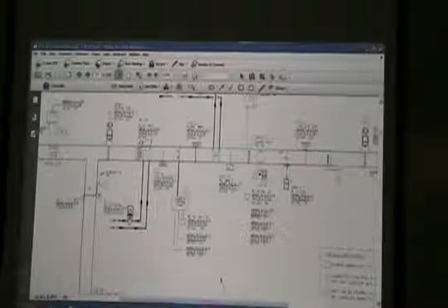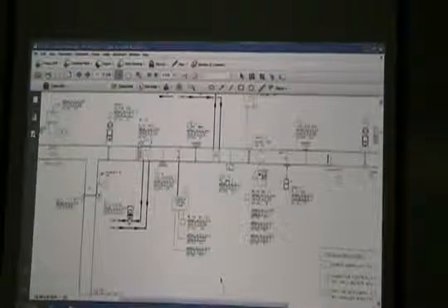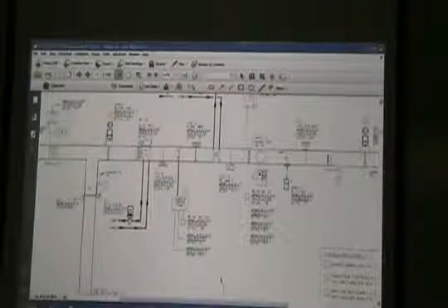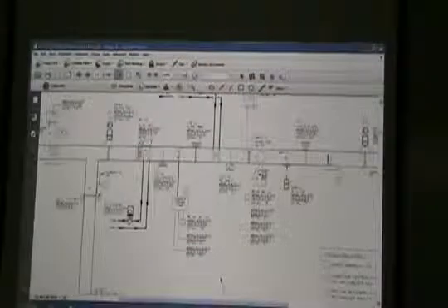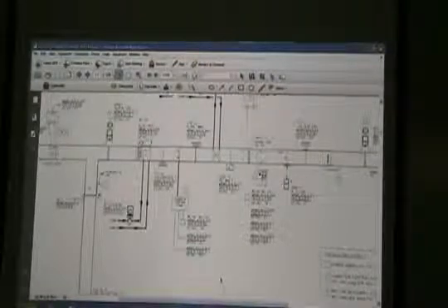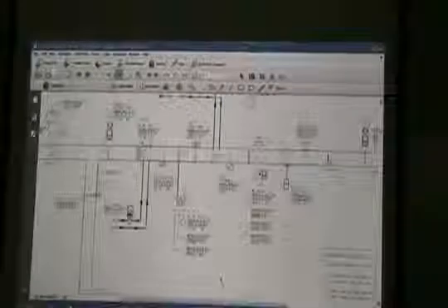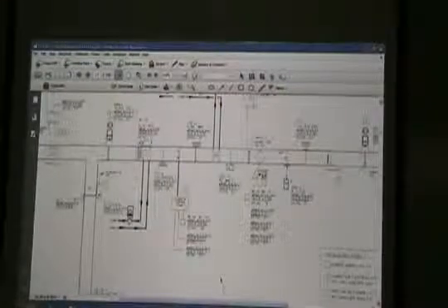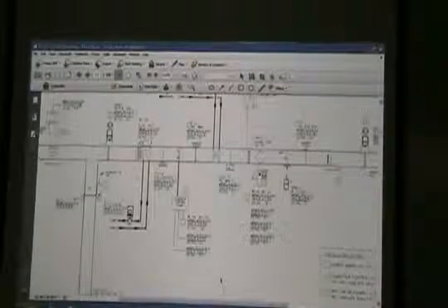All I do is put a shorter coil in there. It's about 2/3 as tall as the cooling coil, and I put a face and a bypass damper. And these dampers probably operate opposite each other, so it could be one jack shaft and one actuator, because one is opening while the other one's closing.